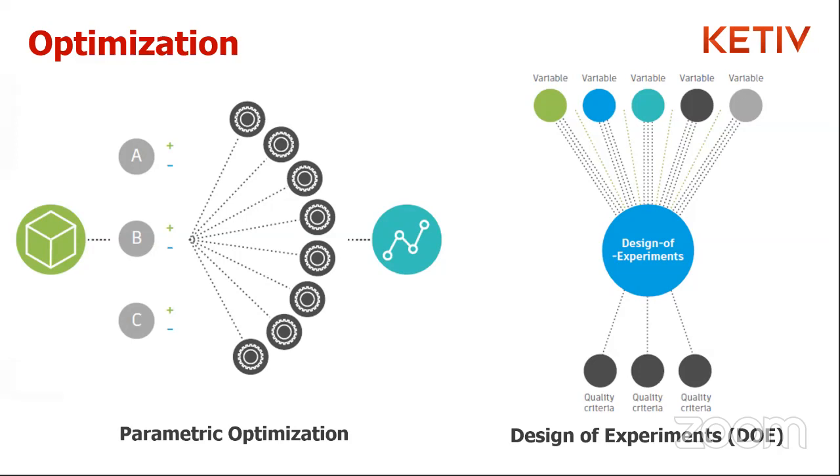So you're even easily able to verify that quickly. With design of experiments, you are running multiple simulations from multiple variables and ultimately having the software filter that down into some easily readable, acceptable results. And most of the time, it comes down to you as the user to choose one of them and select what the best combination of these variables is going to be.